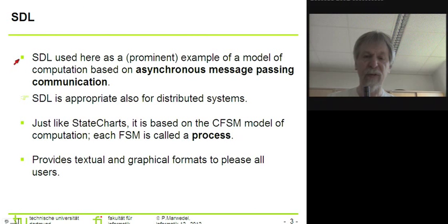So SDL is used here as a very prominent example of a model of computation which is based on asynchronous message passing. So from the general discussion of message passing, we know that SDL therefore is also appropriate for distributed systems. Just like state charts, SDL is based on the finite state machine model of computations, and in the context of SDL, each such finite state machine is called a process.